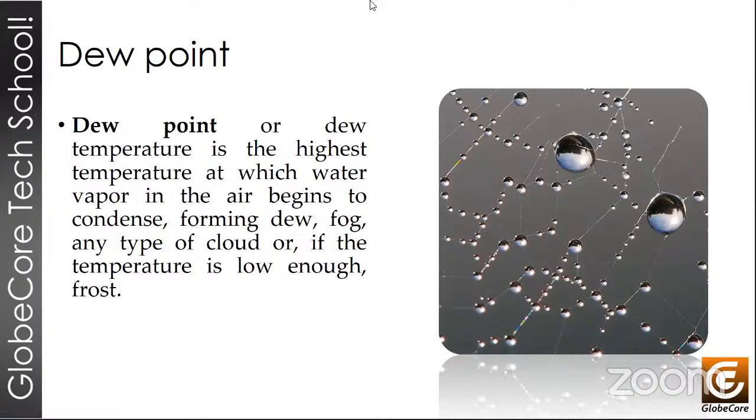So the dew point of a gas, the dew point method. The dew point of a gas is, by definition, the temperature at which the moisture begins to condense on the surface that is in contact with gas. And based on this value, the total amount of water it contains, as well as its relative humidity, can be figured out from a known volume.